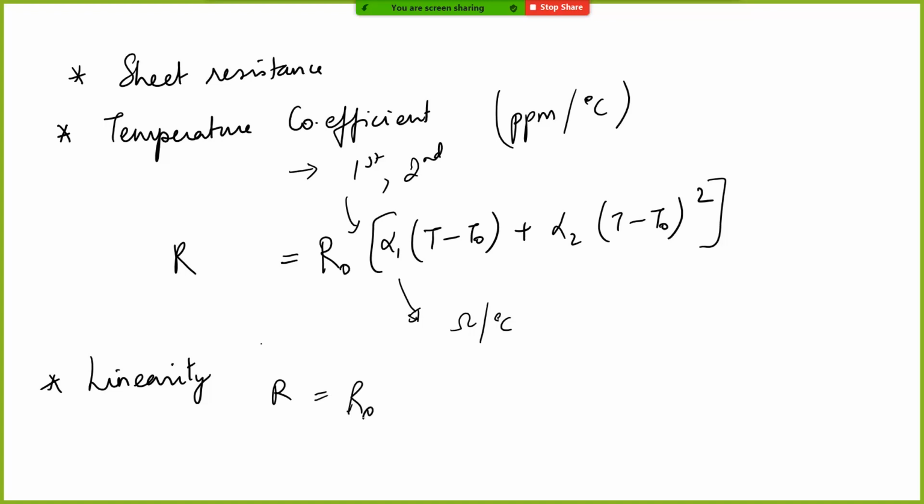So R will also depend on, let's say, this is the nominal value, and it will also depend on some function of the bias voltage and its bias voltage square. That function of voltage will have both V squared terms and V terms. I will show you the expressions, how these things happen, using one PDK as an example. But this is something we have to be a little concerned about if you are looking at very high linearity systems.